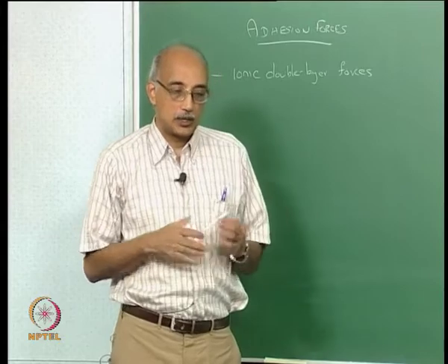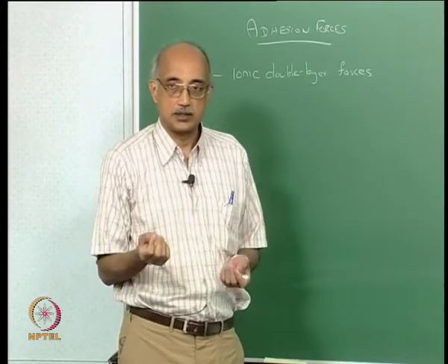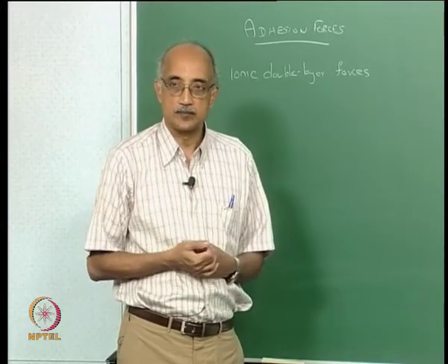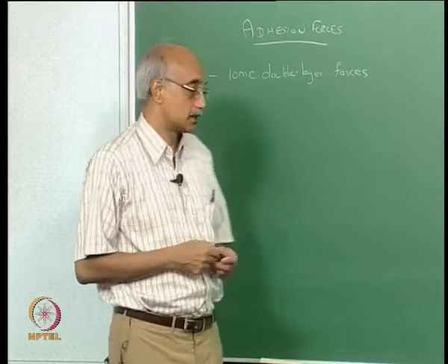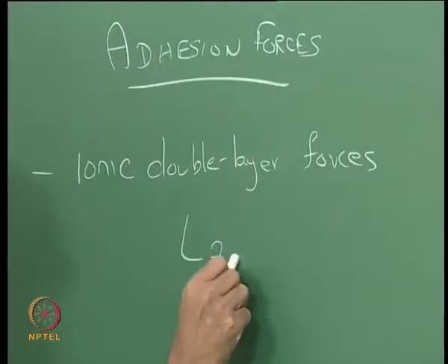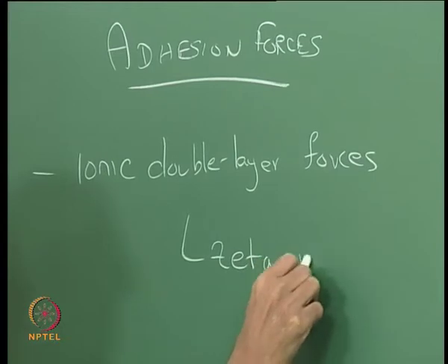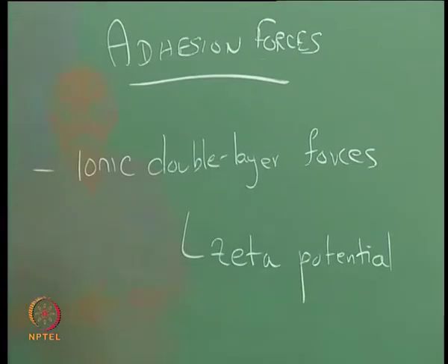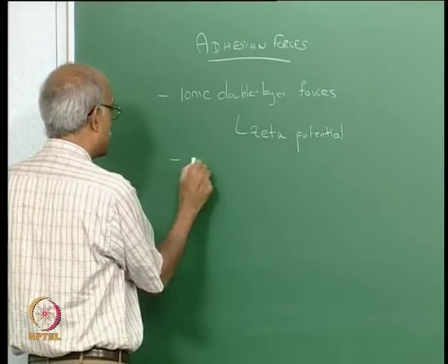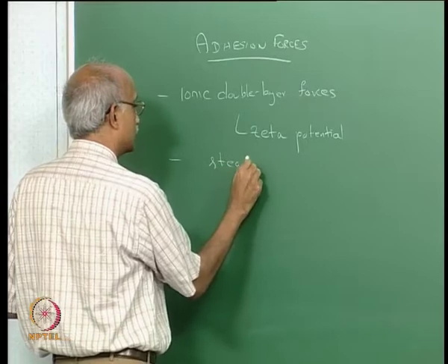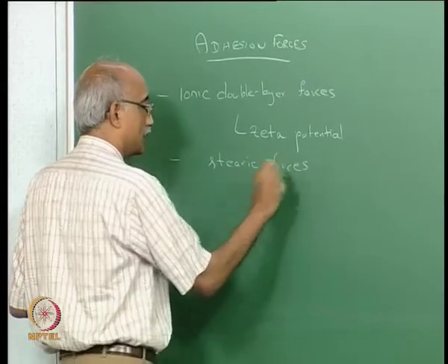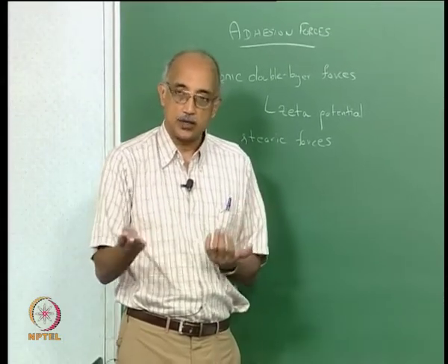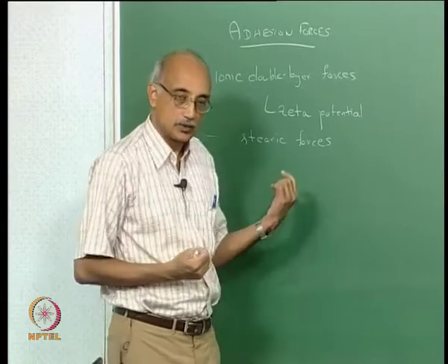Because of the presence of ions in solution which preferentially solvate the particle and the surface, you build up a charge, and that leads to forces of either adhesion or repulsion, and these are represented by zeta potential. Another type of force is what are known as steric forces, which is a name for surface tension based forces. So, the wetting or non-wetting of a surface plays into this.